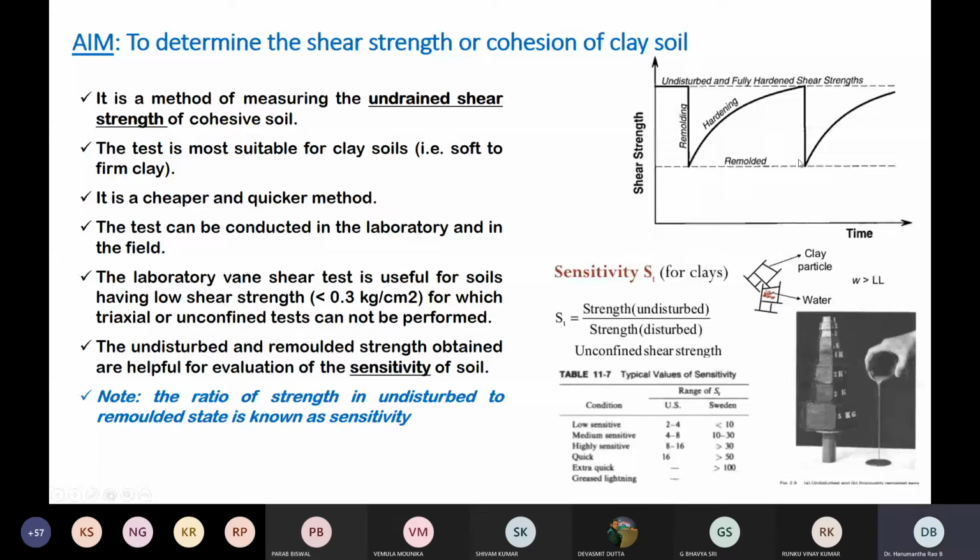The Vane shear will not only be conducted on a soil sample which has been filled in our container, which is for a specific geometry, but you can also conduct a Vane shear test on any other soil sample, as we can see on the left side of our picture, because it depends upon your necessity. So this is a torque ring.